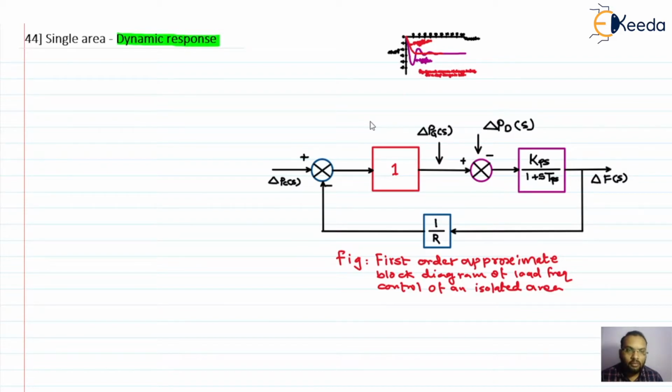In time domain, the advantage is that we get the real values, whereas in the Laplace domain, certain mathematical operations become very simple. That is why sometimes we go for Laplace domain and sometimes for the time domain. But here, in order to understand the dynamic response, we should get the system transfer function in time domain.